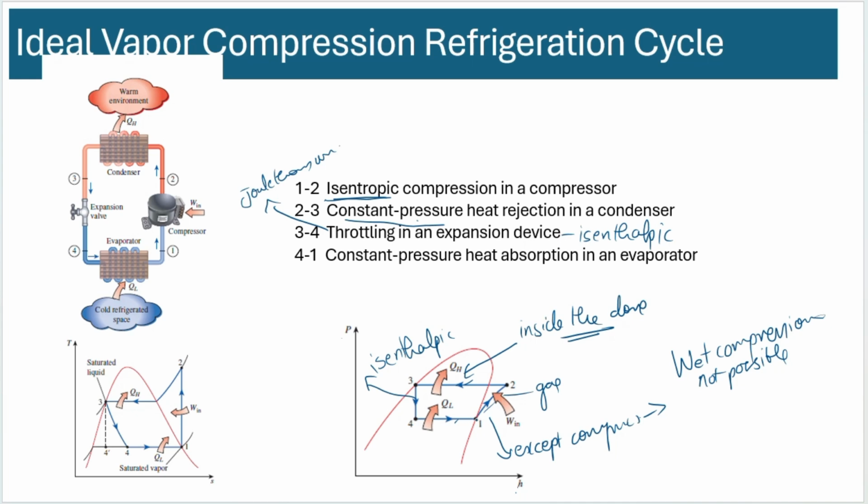So you make sure that whatever liquid is coming to a compressor turns into gas and then does the compression process. And in reality, this cycle is not accurate primarily because isentropic compression can never happen. Typically, compressors have friction. Compressors run really fast, so it's not really slow. It's not in equilibrium. So isentropic compression doesn't happen. Okay, so now that we have looked at all these cycles, let's do some calculations in Excel.